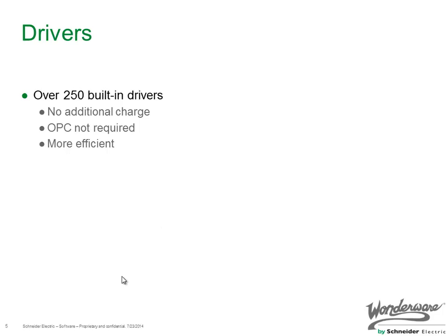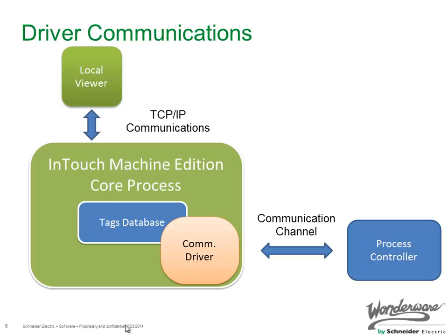There is no additional charge for these drivers, and one of the biggest things to realize about InTouch Machine Edition is that OPC is not required to communicate to an external controller. It's optional. We do support OPC. We support different flavors of OPC, but it's not required. One of the reasons why it's a good idea to use one of the built-in drivers is it's generally more efficient. Having direct communications with the devices instead of through OPC to that end device is often more efficient.